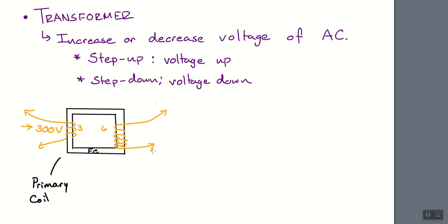Now, as we do this, let's just think about little bits and pieces of it. Forget about the entire right half. You don't have to erase it, just forget about it. I have current moving around a piece of iron which has formed a solenoid. What does it make this iron turn into if we run current in a coil around a piece of iron? It turns into a magnet. Now, we have alternating current, which means it's going from north to south, and it's switching, right? Okay, this whole piece of metal is a super strong magnet. Everybody cool with that? On the other side of this, I have another coil that is now working within a magnet that the field keeps switching.